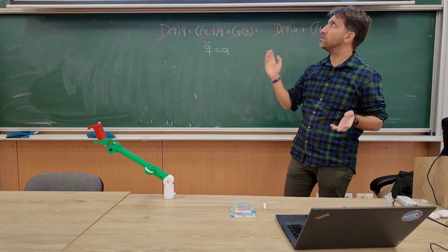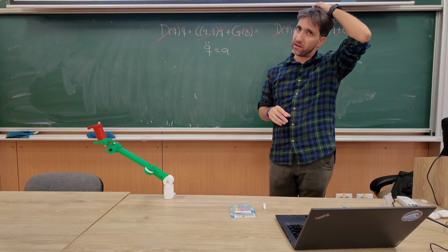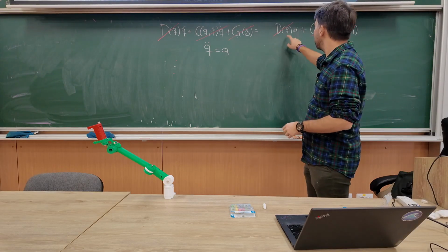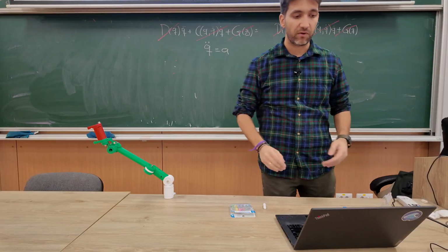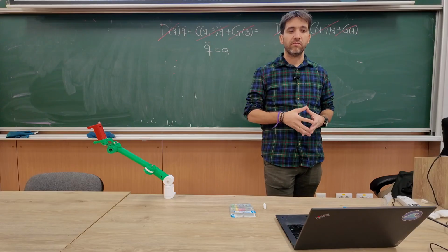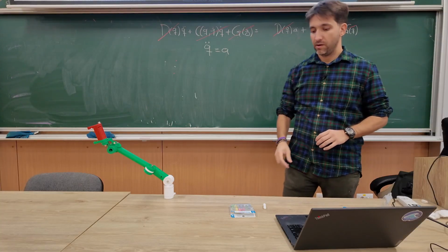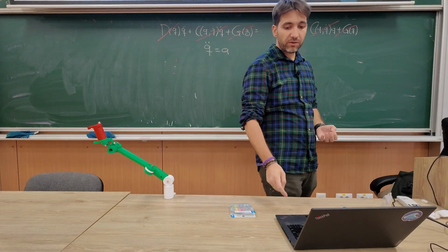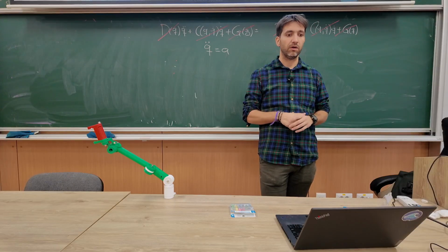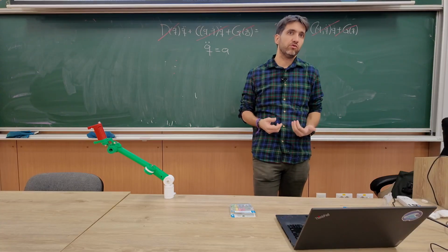And we have what we call system or feedback linearization or dynamic linearization, whatever. It's basically, we don't linearize at a specific equilibrium point like you were saying, we linearize at any point, right? Because we can linearize for any Q and Q dot here. But it's not necessarily a perfect linearization, right? It will be a good linearization as long as the model is good. So basically we use knowledge of the model in order to linearize the real process. And again, as long as the model is good enough, this will be a good linearization.